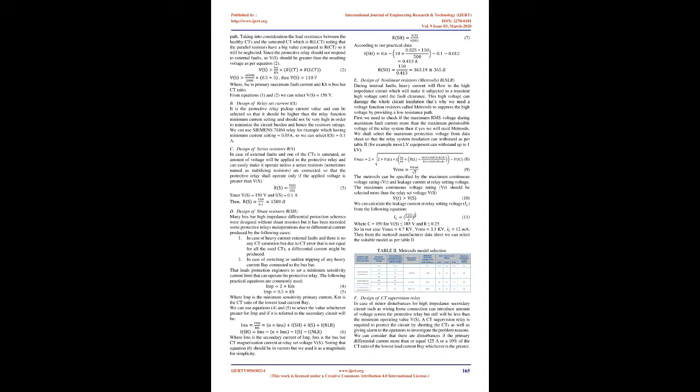V_S < 1/2 V_K (equation 1). In case of external faults, heavy currents will flow through the system bays, resulting in zero current difference in CTs theoretically. But in the practical case there is a possibility for at least one CT to be saturated. In this case all CTs' summation current will flow through the saturated CT, which is specified by its secondary resistance R_CT, as it is the smallest resistance